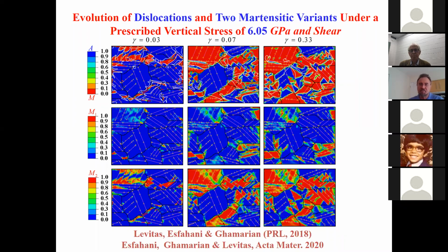But you don't need high pressure. You can do any plastic deformation, a traditional method, and it will work. And that is what is done in applications for shape memory alloys. It's called ausforming and marforming. This is plastic deformation of austenite or plastic deformation of martensite. And this also controls martensitic transformation stress and temperature.